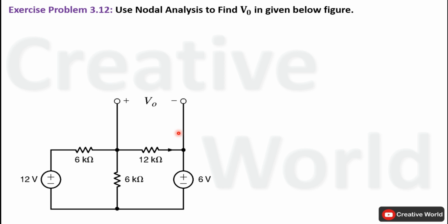We know that in order to apply nodal analysis on any network, we have to follow some steps. First step includes finding out the maximum number of node voltage equations that can be retrieved from that network. So using this equation we can find that figure. In this equation n represents number of nodes in the network. So in our case there are two nodes. 2 minus 1 will be equal to 1. So maximum one node voltage equation can be retrieved from this network.